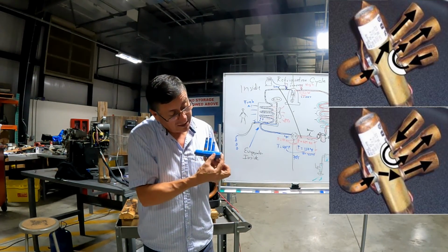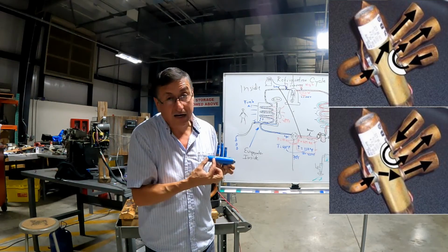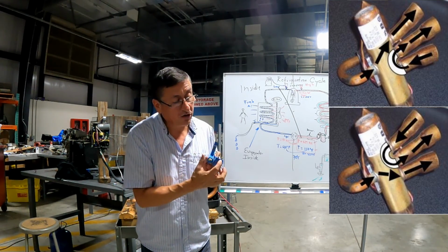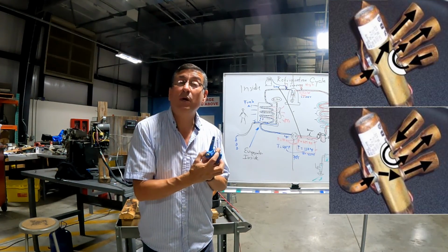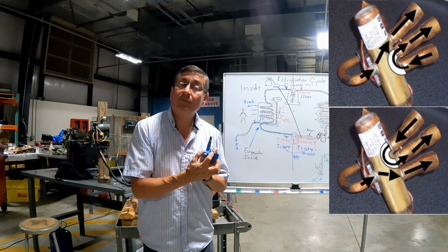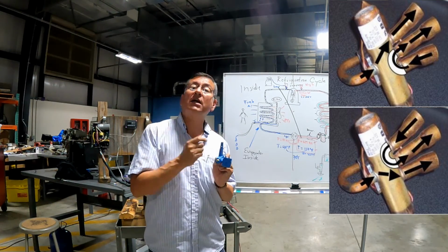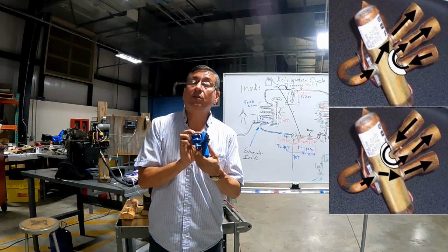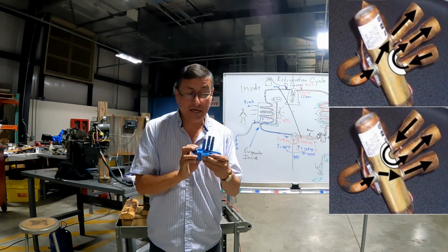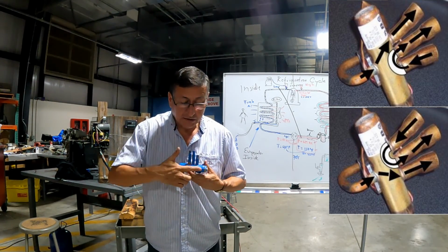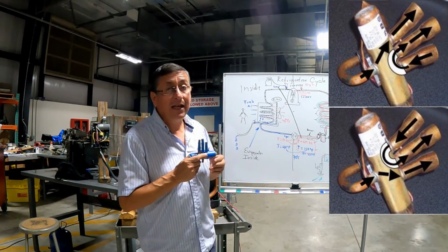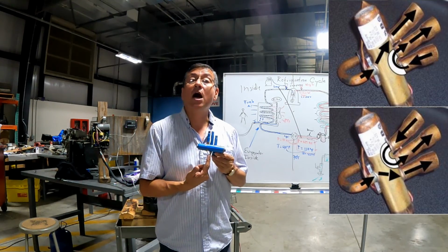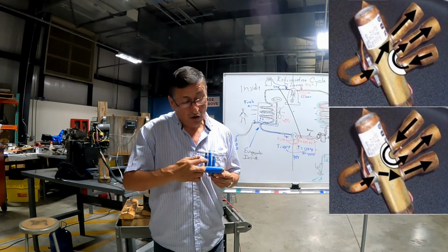This is possible because this element moves here or here with a solenoid, and this is the solenoid. The solenoid receives a signal between 28 and 30 volts AC. That signal is coming from the computer of the air conditioning system. This AC signal between 28 and 30 volts AC moves that metallic element inside of the Y valve. This is the input of the refrigerant coming from the output of the compressor.